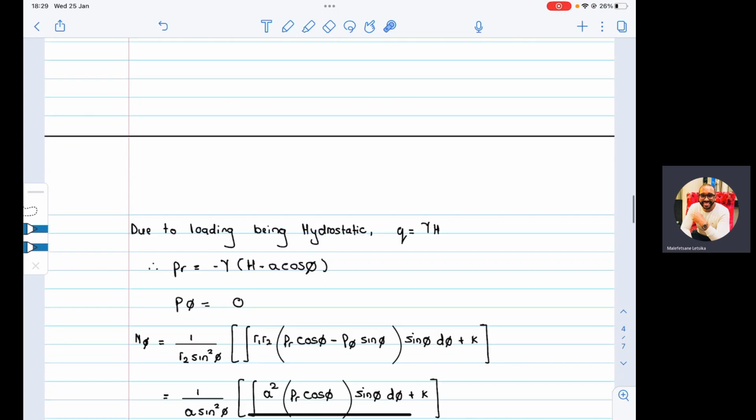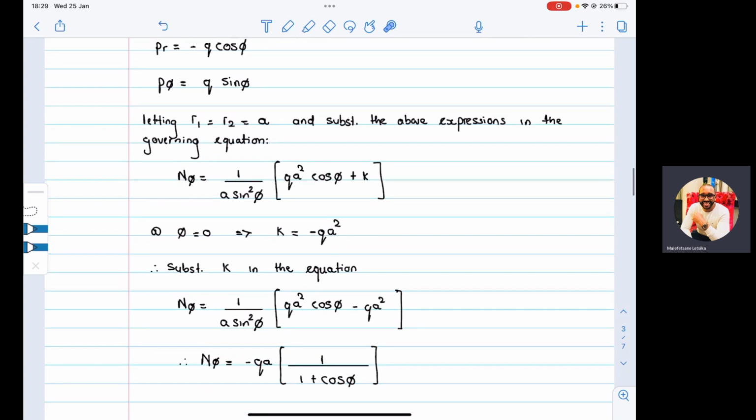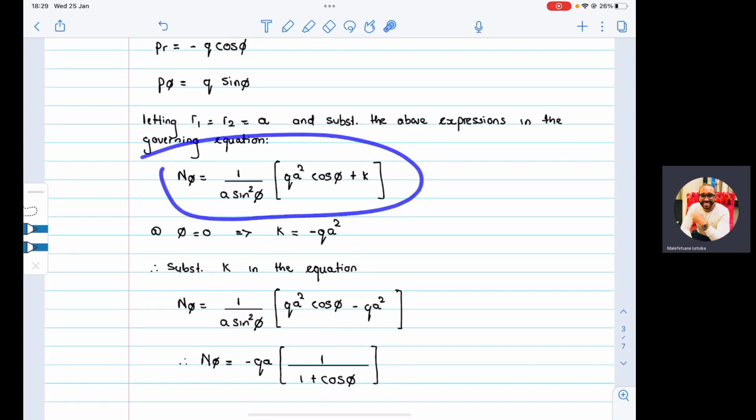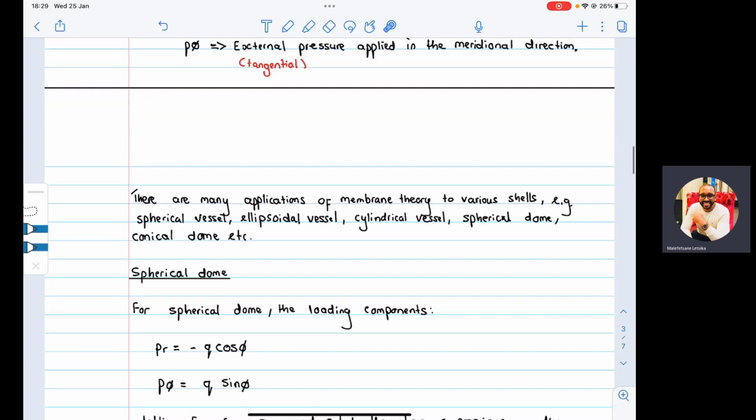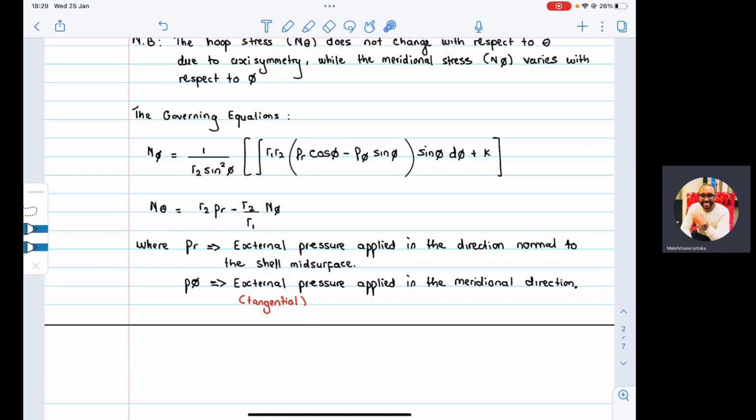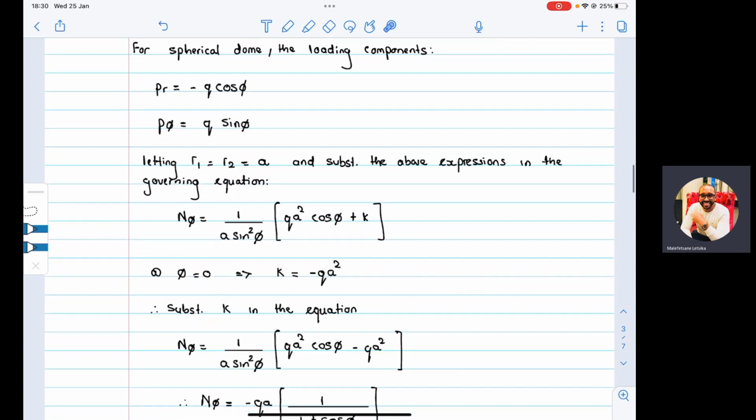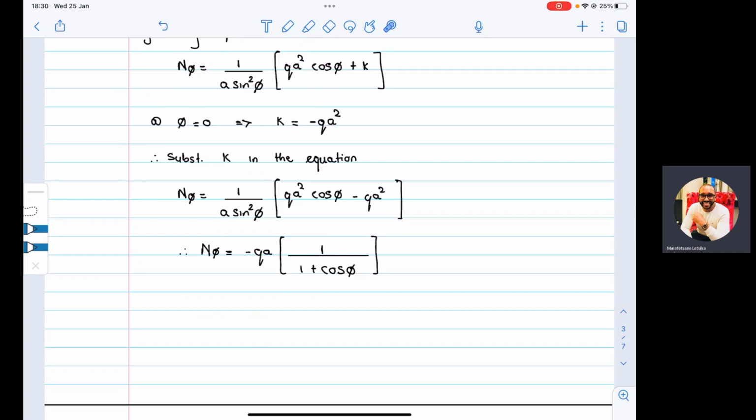Okay, so please, when you analyze spherical domes, you can't just take this general formula. You need to go to the main generic version of the meridional stress resultant equation, which is this one. This is the main engine. Whatever you solve, could be spherical, conical, you always go back to that. Of course, if you solve it for meridional stress.